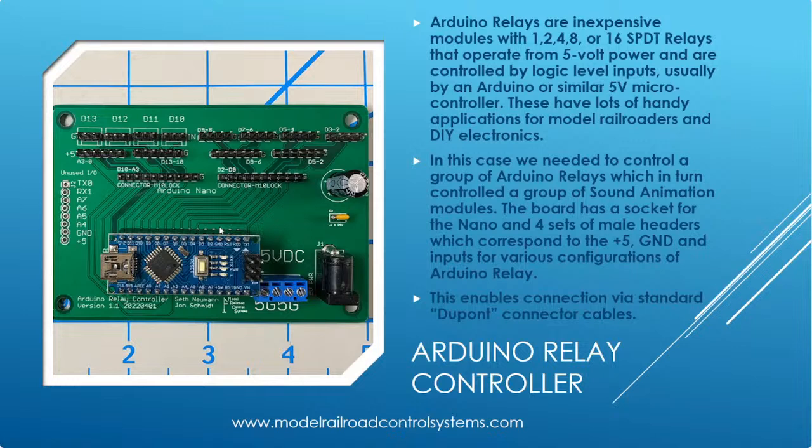And they have ribbon cables, which makes wiring them together a snap. And they have several different patterns, but they all basically are ground, bunch of outputs, and power. And so what we've done is just provided various combinations of outputs so you can optimize the use of outputs on your Nano, and then it will control these relays.